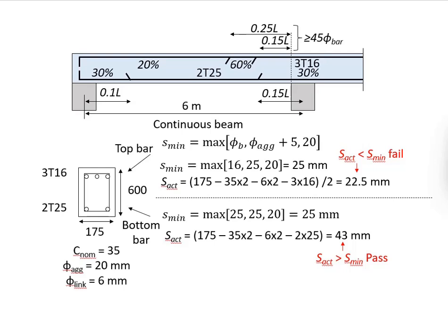Now, one principle of arranging the reinforcement is that you have to arrange the reinforcement in a symmetrical manner. You cannot simply move the 1T16 here or here. That will give you an unsymmetrical arrangement of the reinforcement. You have two options here. Either you increase one reinforcement bar with 16 mm diameter, make it an even number, so that you can have one reinforcement bar here and another reinforcement bar here without having the center reinforcement. This gives you a symmetrical arrangement of the reinforcement.